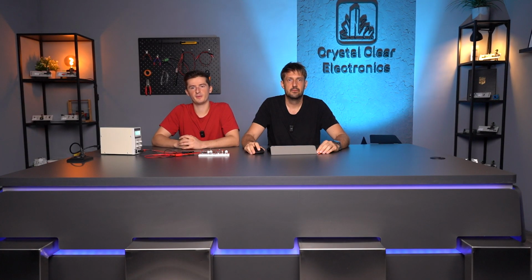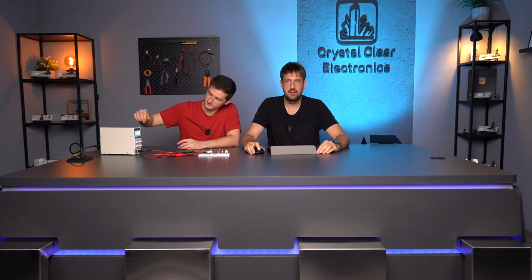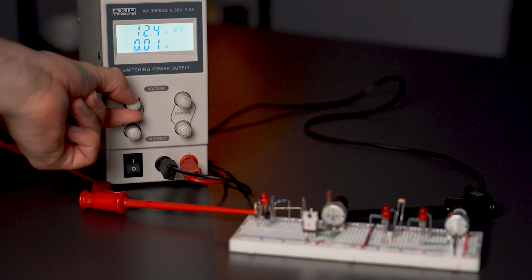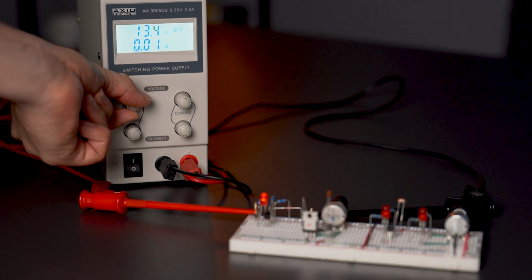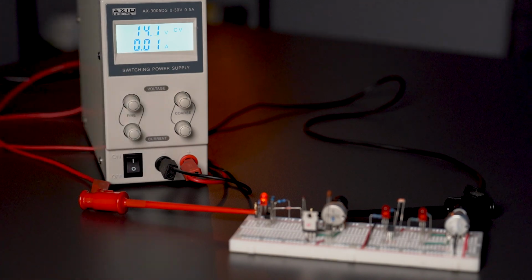The theoretical voltage required to open the transistor is 2 times 3.3 volts plus 0.6 volts, which is 7.2 volts, which means that the transistor would open at an input voltage of 14.4 volts. In practice, the tolerance of the components again affects the operation. At a 12-volt input, the LED is already glowing faintly, and at around 13 volts, it is clearly visible that it is lit.